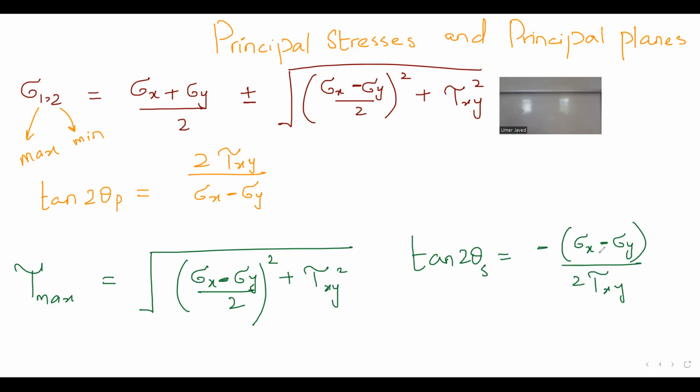As we were feeling very confident that we have made that wooden stick in such a fashion that it might sustain this load that we are putting, it chooses to break at a 45 degree plane, which is your maximum. So it is possible that your object can break on the maximum shear plane.